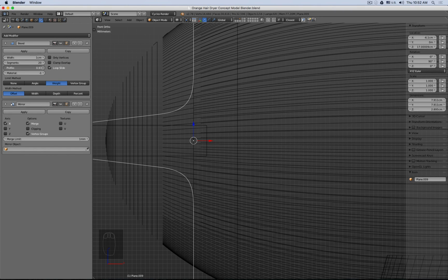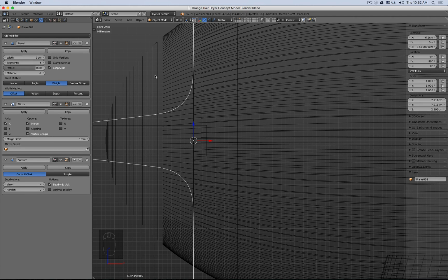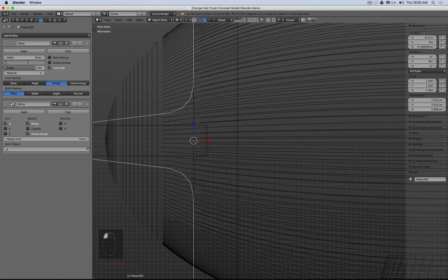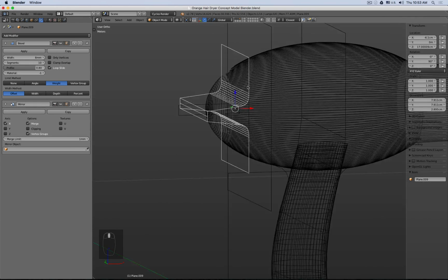So, instead of working with loop cuts, in this case, I simply work with the bevel command, add more bevels, adjust the profile. I only need 5 because later when I add the T-spline module, it makes it nice and smooth. I can play also with the radius, so it's pretty great the way how it works. Okay, good.